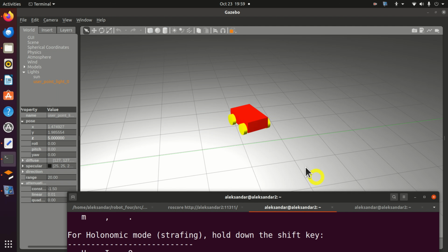Behind the scenes, there are several ROS nodes that are running and that enable us to control the robot and observe robot states. The control actions are actually sent as a twist ROS data structure that is converted to mechanical motion by using the so-called Gazebo skid steer drive controller. The model developed in this video tutorial can be improved by including cameras, sensors, lidars, navigation, and SLAM algorithms. We will cover these topics in our future tutorials.